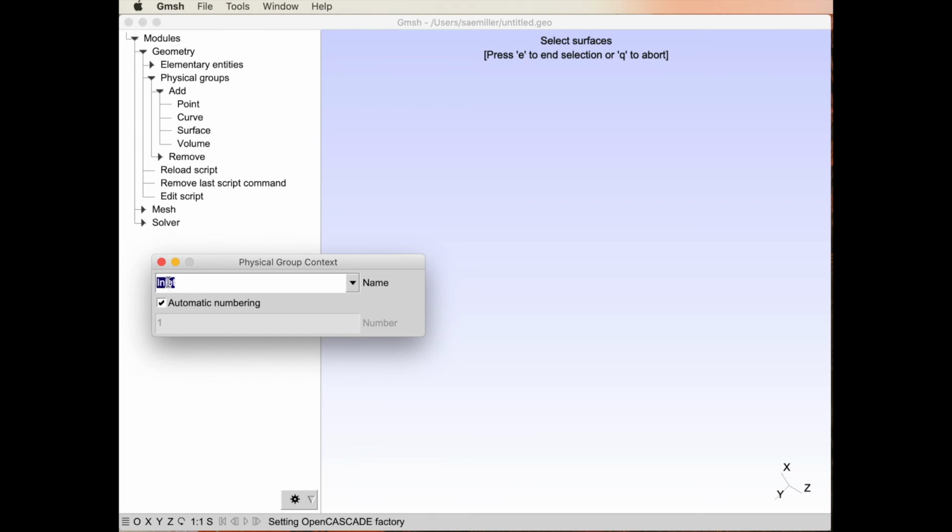Now, these names are also shown in the name list of, say, the CFD solver. So when the CFD solver reads this grid file and boundary condition file, it could see the word inlet, and you would tell the CFD solver that inlet means an inlet boundary condition. So we'll apply some boundary conditions later to show you how this is done.